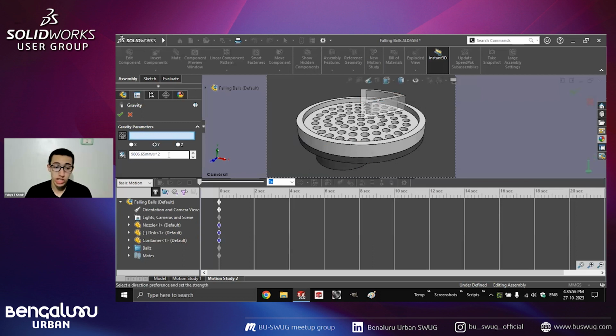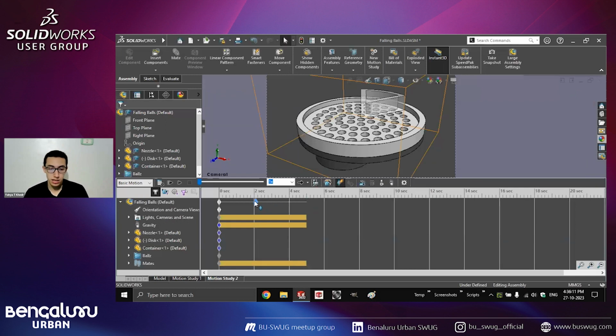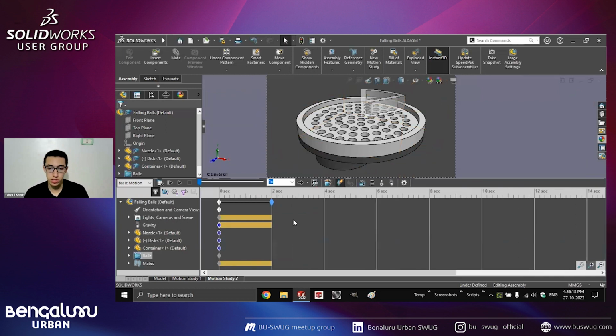So I can also change the value. The default value is obviously the g of Earth, the gravitational acceleration, but you can also change it to, let's say, the gravity of the moon or any arbitrary value you want to use. So I'm just going to hit OK. And now what I'm going to do is hit calculate.